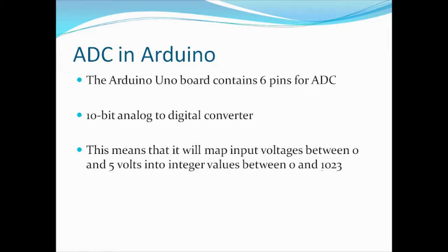It is a 10-bit analog to digital converter. This means that it will map input voltages between 0 and 5 volts into integer values between 0 and 1023. That stands for 1024 values, so from 0 to 1023 it can come.